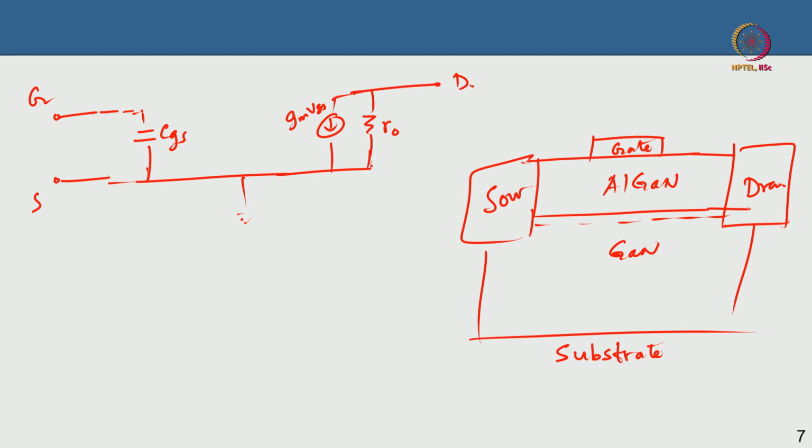Now remember, this model was invoked from the basic 2 port, the linearization of the nonlinear part, and invoking the I matrix, the Y matrix and the V matrix, remember V1, V2, etc. and Y11. We were using a mathematical model, and then we developed this small signal model from there. So it's forming from that point. It's not magically appearing out of anywhere.